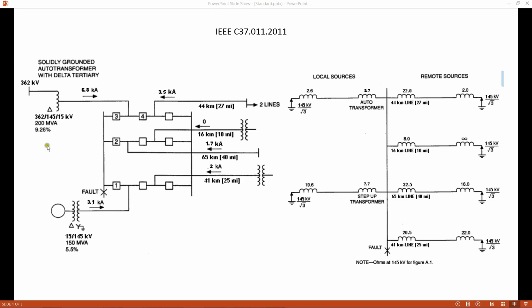And to finish, I will do the same case but with a frequency dependent model of line. We will see that here we are pessimistic because we use parameters that are valid only at 60 Hz. After, we use the frequency dependent model of line, and for high frequency the inductance and resistance change, and in the end it's less pessimistic than the case here.